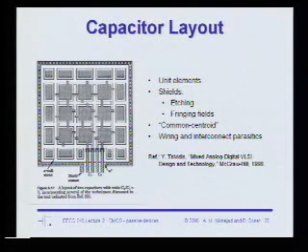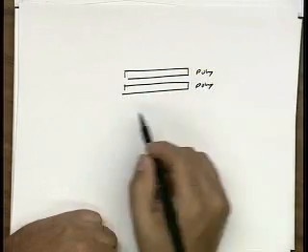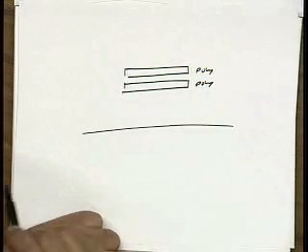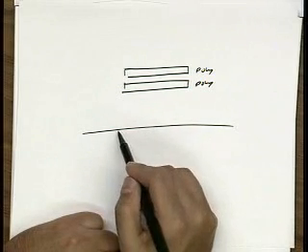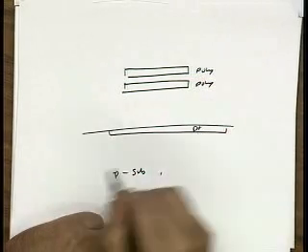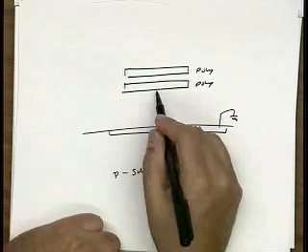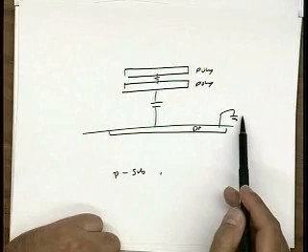Yes. What's that ring surrounding the whole structure? The ring around it, that's the shield. So again, this is a poly-poly capacitor, and there's a back plate. And if I don't put anything down, then this will just go to substrate, right? But what I can do is I can actually put a diffusion here. Let's say this is a P substrate. I can put a P plus and ground this point. And so now I have a very well-defined place where my backplate parasitic is grounded.